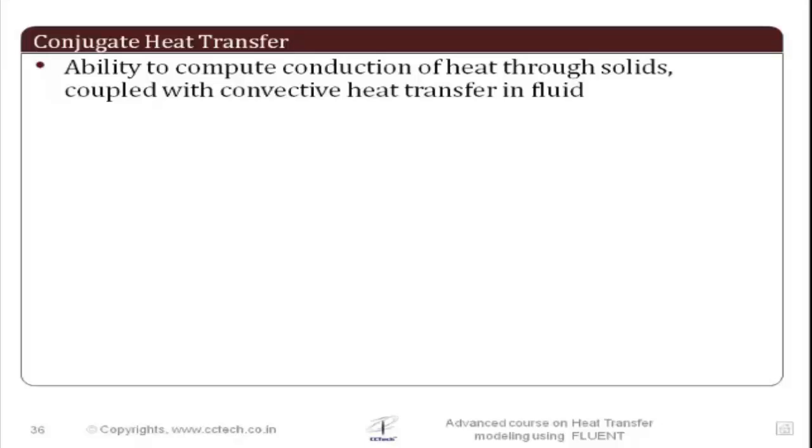The next topic that we are going to discuss is conjugate heat transfer. Conjugate heat transfer is nothing but the ability to compute conduction of heat through solids, and it is coupled with convective heat transfer. So when we are solving conduction along with convection, that is conduction through solids and convection through fluid, that is referred to as conjugate heat transfer.